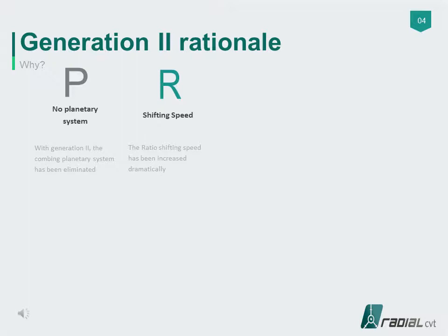Currently, such dual-mode synchronous systems are realized by utilizing a planetary power split configuration with a downside of multiple wet clutches, as well as circulating power and torque, which has a negative effect on transmission efficiency.